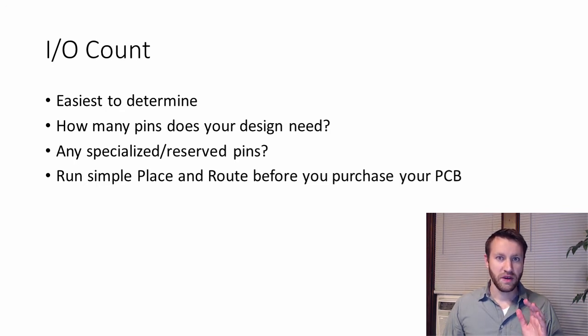And one piece of advice that I would give in this situation is run a basic place and route before you purchase your PCB, before you purchase your physical design printed circuit board. Run a super basic place and route that just makes sure that your clock input pins, there's special pins on an FPGA that are reserved for clock inputs. Just make sure that you correctly assigned the clocks to be on those pins and that that's able to drive flip-flops, and your SD-RAM is properly wired up. You don't have to run it and make sure that it's working correctly necessarily, but just to make sure that the general place and route is correct.